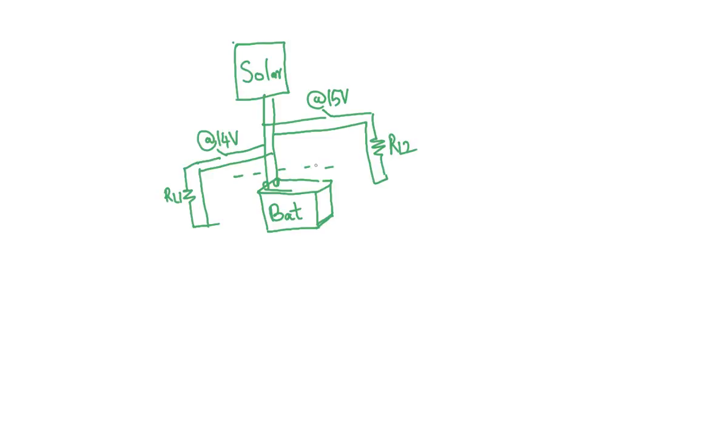So then you need basically something that is a comparator. You want to look at the input battery voltage. So I somehow generate some version of 14 volts. One simple way of doing that is putting a resistor divider. Maybe you compare to something more reasonable. Let's say you divide it by 2.